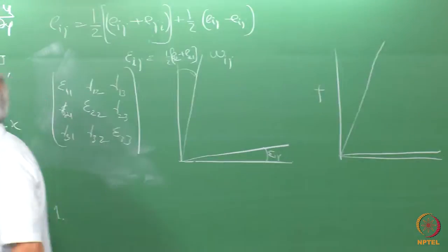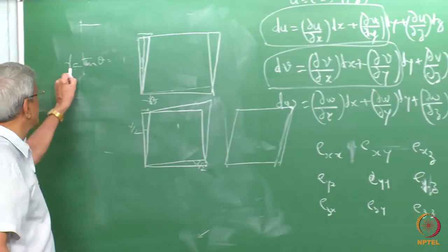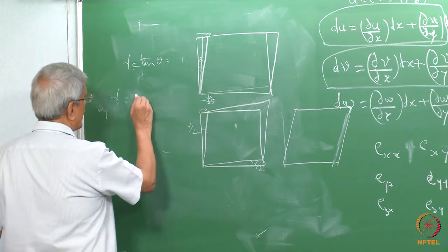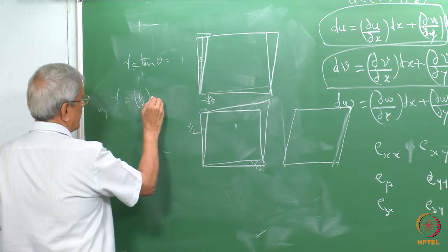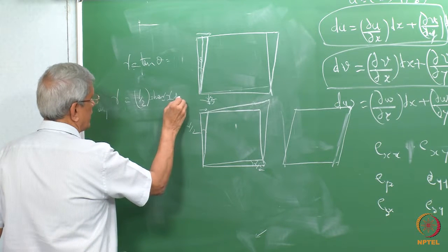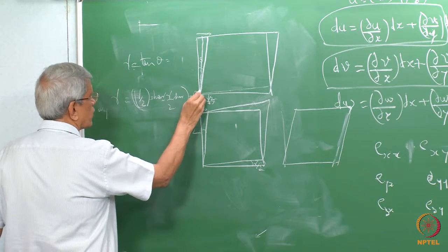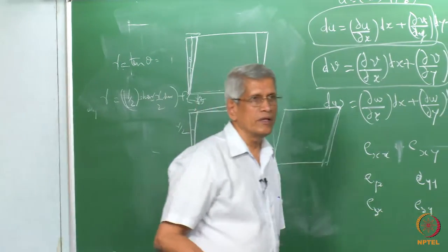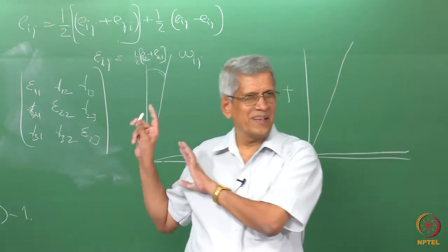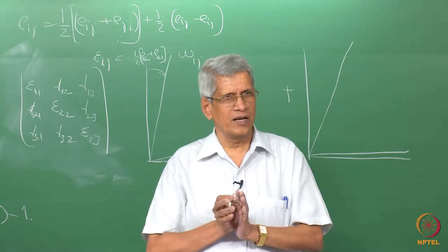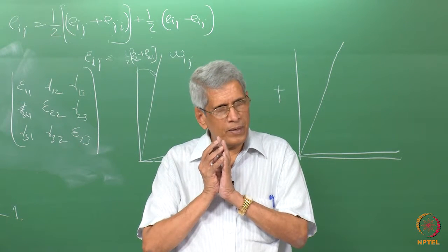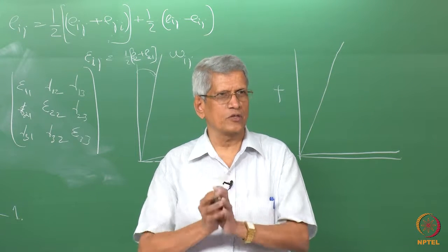The reason essentially is that here, if you take this gamma engineering strain, it is nothing but equivalent to giving, in any particular direction, a shear of gamma by 2, a shear of gamma by 2 in another direction, plus a rotation of gamma by 2. You understand that? So both don't become equal. So use only the pure strain. If you wanted to find out just the strain part of it, use the strain. The definition which is given by the strain tensor only has to be used.